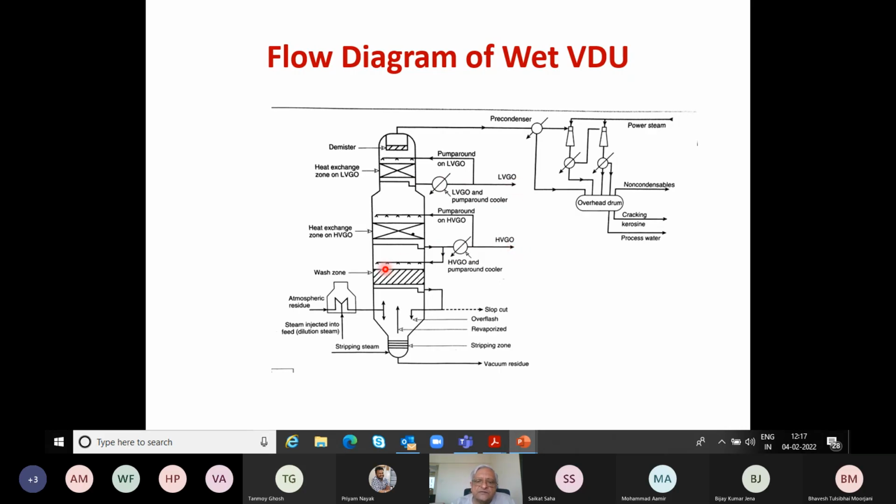There are three good reasons for that, and all three are linked with the economics of this vacuum tower. Remember, this vacuum tower is at a very high vacuum, and because of that, the vapor flow velocities are high. So in order to have reasonable vapor velocities, we have a pretty large diameter for these vacuum towers. Some can be as large as 20-meter diameter.